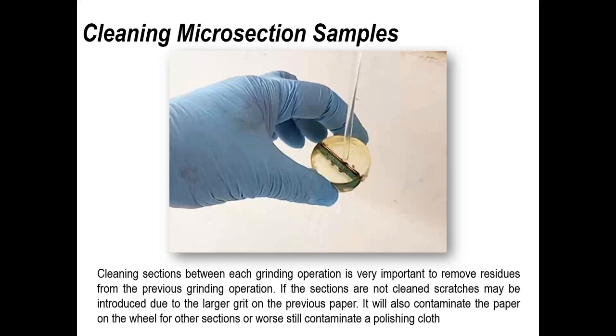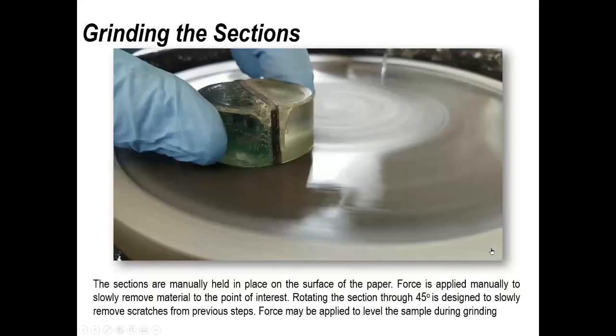So always wash between each step, each stage, each paper, each polishing stage, just to minimize the possibility of any damage you're introducing to your sample.